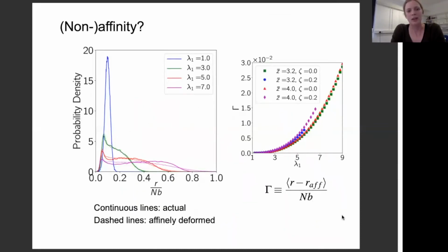Now, one of the directions for improving continuum theories for rubber elasticity is to try to remove this assumption of affine deformation of the chains, which is often used. So we wanted to see if deviation from affinity was a thing, at least in our random networks, because although at small deformation you can demonstrate that all the chains should deform affinely, when they are in the regime where the force-extension relationship is linear, when you go to high stretches and the force-extension relationship becomes non-linear, you're not sure that you will still have affine deformation of all the chains.